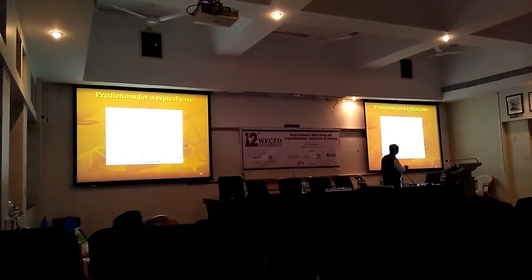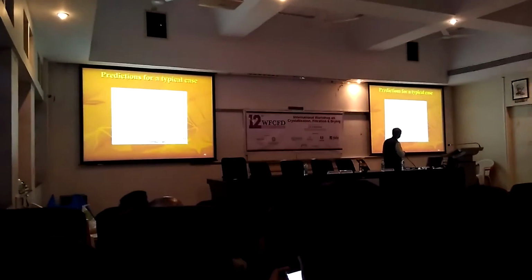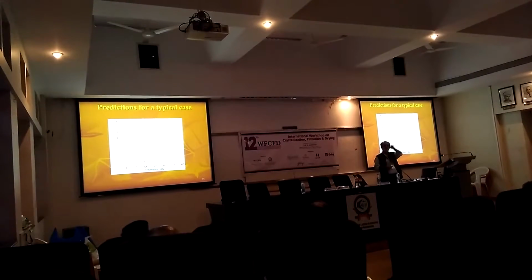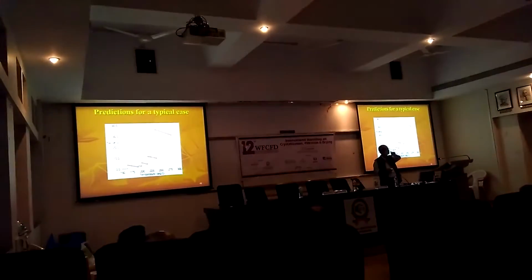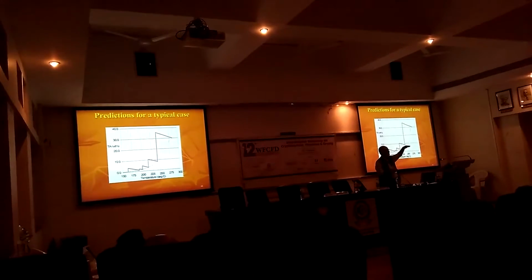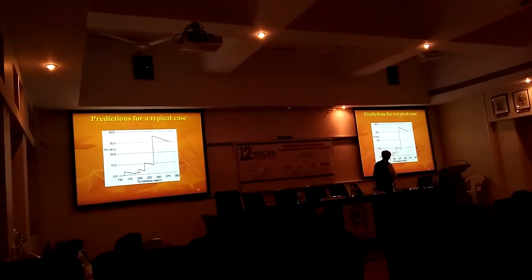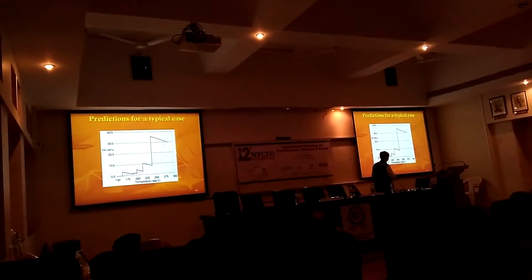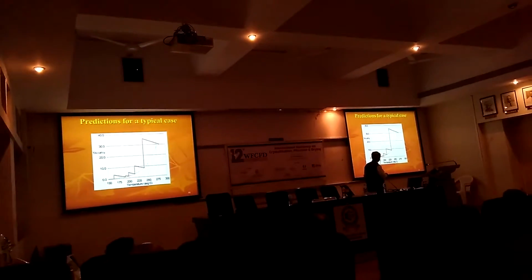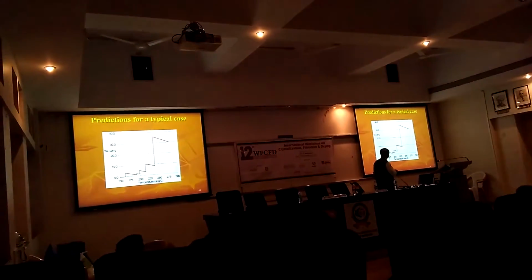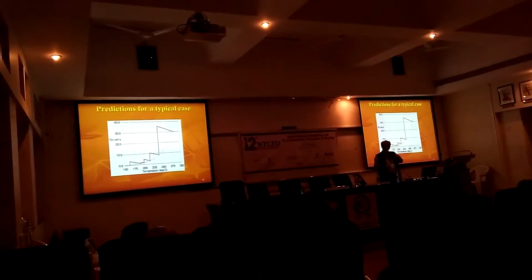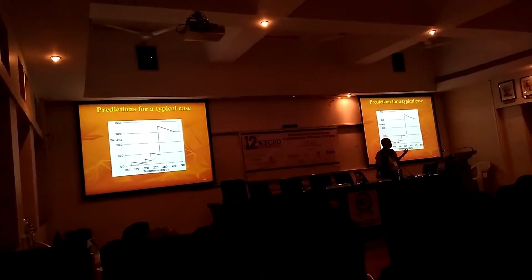So usually this is your circulation curve or solubility curve or the equilibrium curve. You tend to operate it in a stage-wise manner, which is very similar to the initial graph which I had showed you, starting from unsaturated liquid, either you evaporate it or cool it. It is sort of a step. You allow a certain quantity of material at a constant temperature, evaporate the solvent, then allow the material to crystallize out, evaporate some more solvent, allow the material to crystallize out, and you can keep on doing this. But you can imagine now this is stage wise. When it is stage wise, what is the utility?